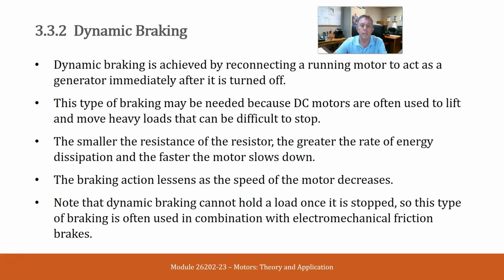Dynamic braking is achieved by reconnecting a running motor to act as a generator immediately after it's turned off. This type of braking may be needed because DC motors are often used to lift and move heavy loads that can be difficult to stop.